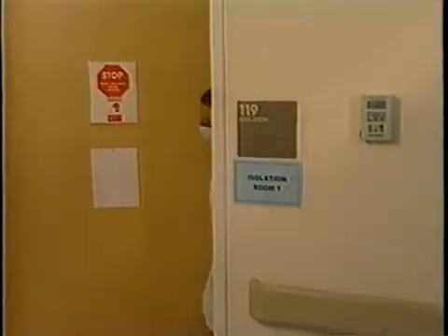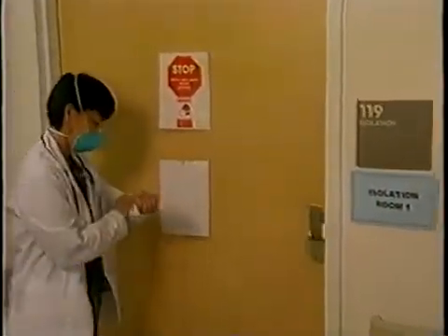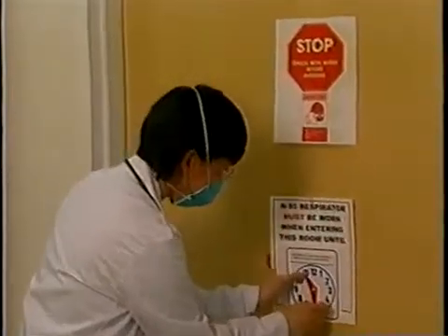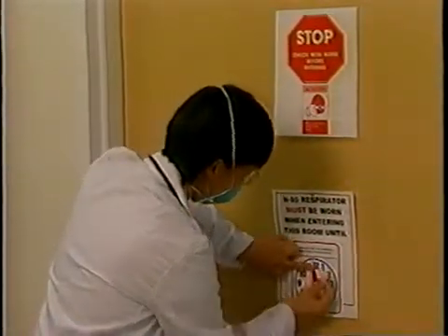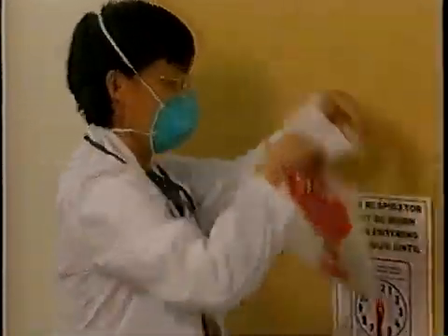When an infectious TB patient walks out of an isolation room or a sputum booth, he or she may leave some airborne infectious particles behind. Before another patient or a staff member enters the room without wearing a respirator, you must allow sufficient clearance time for the ventilation system to remove most of these particles.